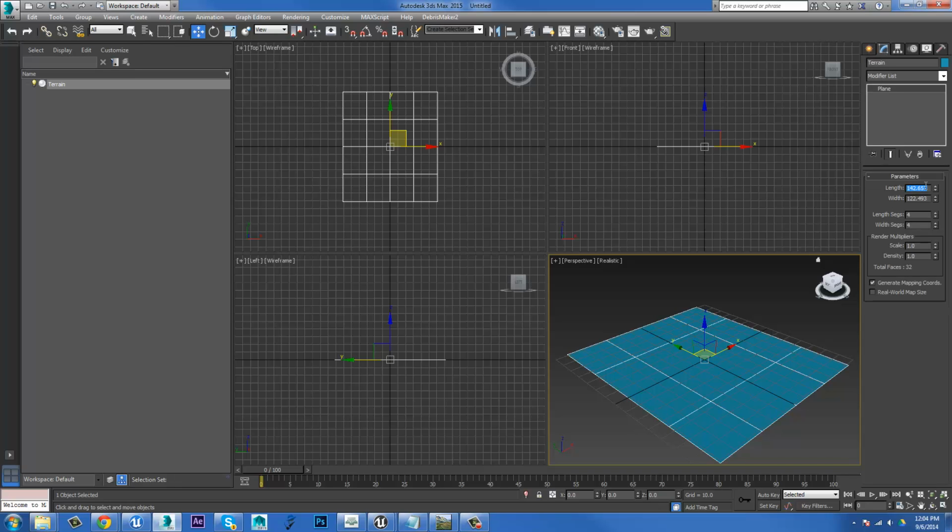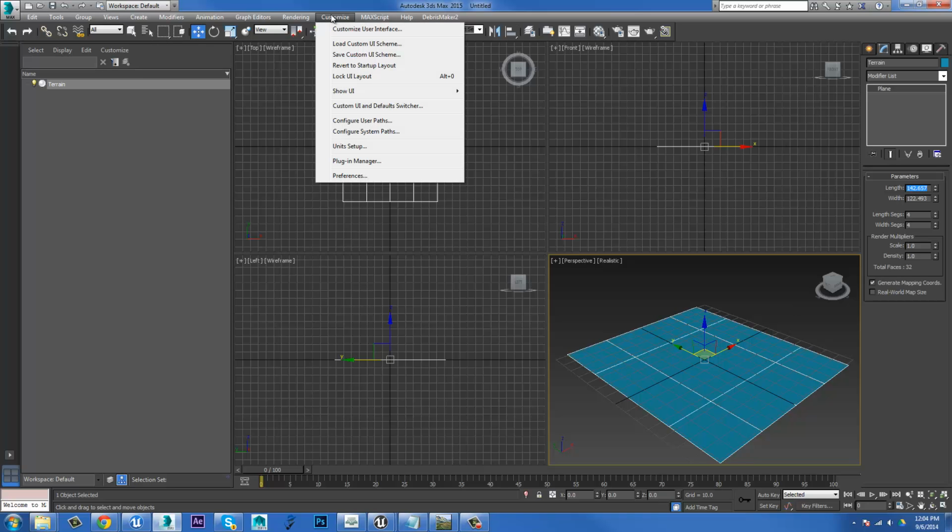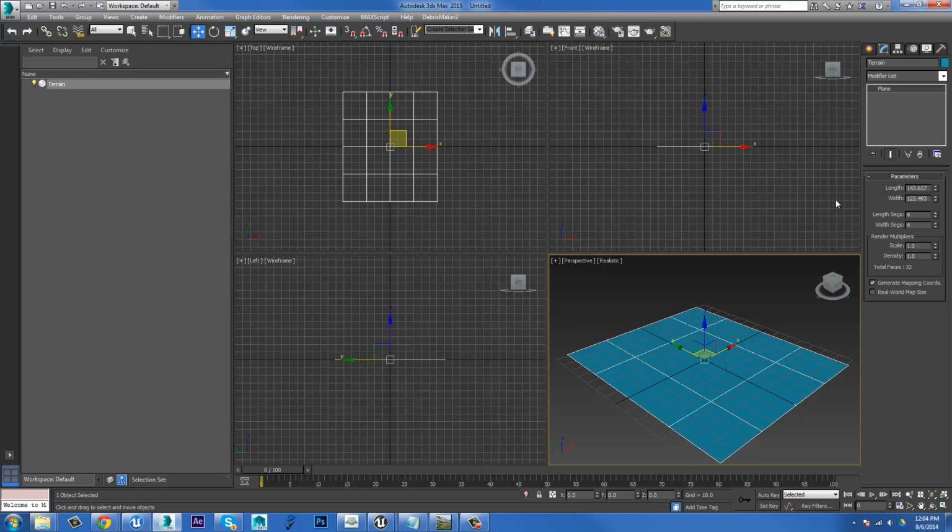In the properties for that terrain, now the texture I created was 1025 by 1025 and my Max is currently working in centimeters. So if I did that now, it would be about 1.5 meters. I could set my Max units to be meters or kilometers and get it all completely accurate. For the moment, I'm not going to worry about it because I know that this works and it's totally fine. You could always scale the object up if you needed to. And if you make it too big to start with, you're going to end up with camera clipping issues. You won't actually be able to see the whole thing. So, work the way you want to. I'm not the boss here.